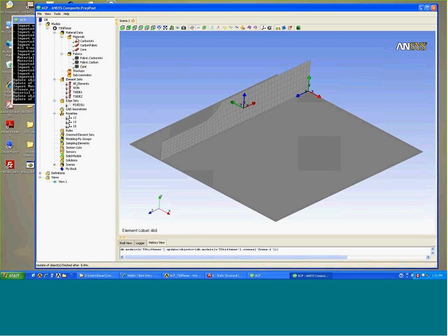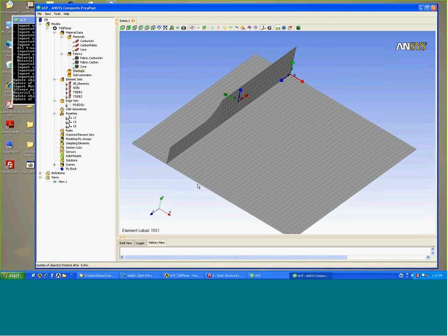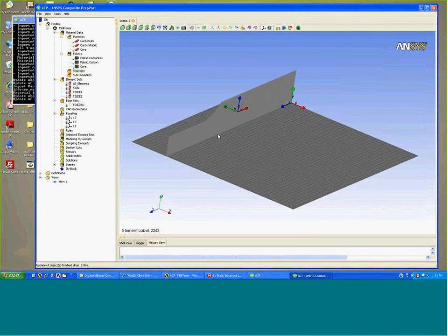Next, within the material data category, we have stackups and sublaminates. This allows you to define essentially a hierarchical list of combinations of fabrics and perhaps groups of stackups and sublaminates. And as an example, I'd like to use a stackup in this particular problem for the flat skin here. Imagine a T that we have, the T blade here, we have two legs of the T, and also we have an overall large or gross area skin. In the skin, I would like to build up a honeycomb core with face sheets and then the solid laminate T on top of that.